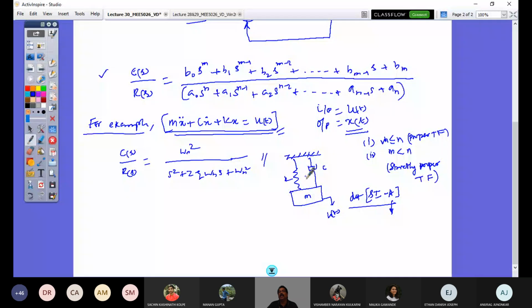If I look at my unsprung mass and then sprung mass, we will see that in detail in our ride dynamics part. So I can also represent my vehicle as a single degree of freedom model. If I consider that, I can work out for this bounce. The next detailed model is what is called the quarter car model and so on. That we will see as a vibration model separately. But now if I have this equation, how do I get my transfer function?